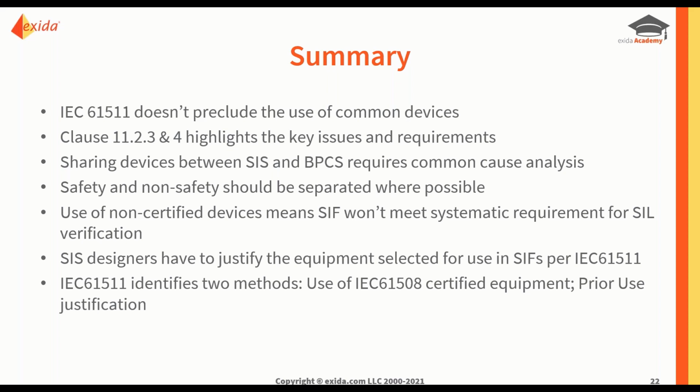So here again, when you share sensors, for example, sensors normally are not the major contributor to the overall PFD average. It's normally the final elements that have the highest PFD average contribution. So with sensors, and this happens a lot, they use splitters and things like that to share sensors. You would still have to do some form of analysis. And again, remember that if it's not a certified device, it's going to have an issue from a systematic point of view.